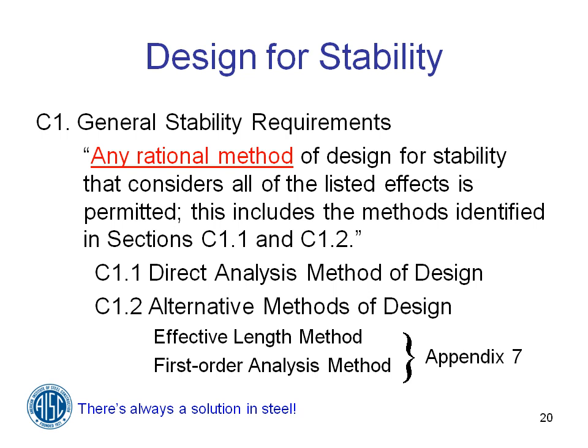And it then references you to Appendix 7, where we have the effective length method and the first order analysis method. Now this organization is a little bit different than the organization that you saw in the 2005 specifications, but the provisions are essentially the same.